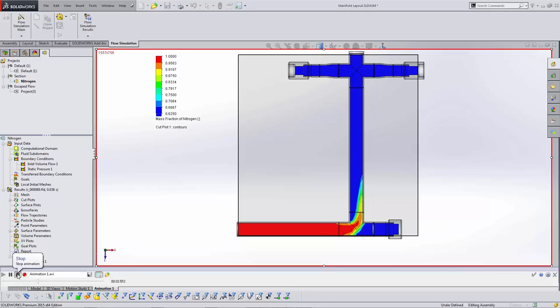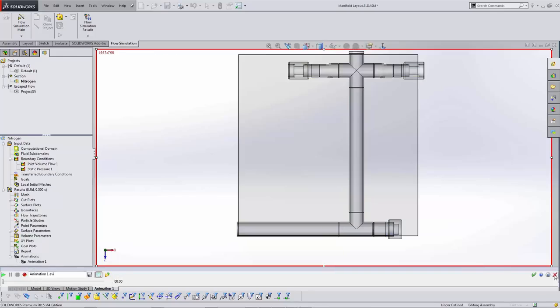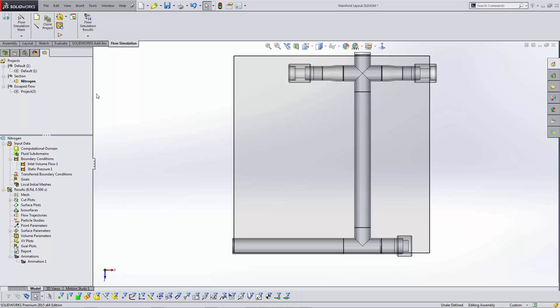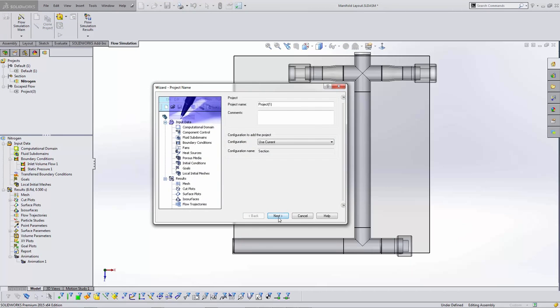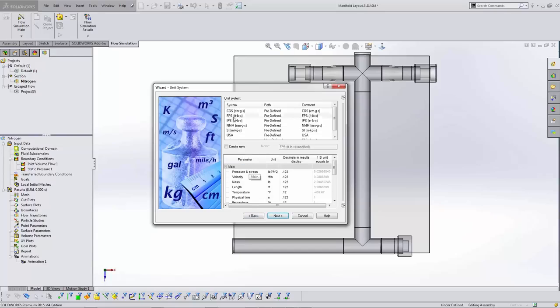Now the important thing to realize here is that I do have lids closing off the ends of these pipes. This is not an external analysis. Those lids will still allow the nitrogen to push the methane and ethane out of the system, so it can still work as an internal analysis.